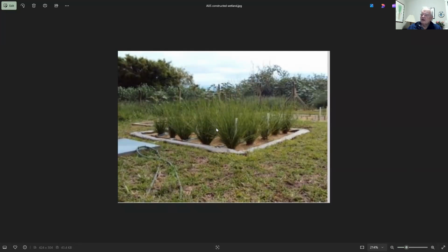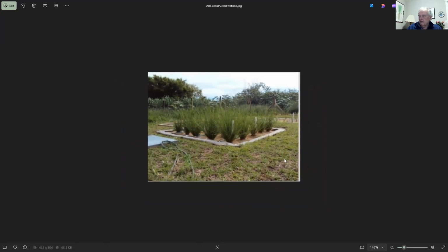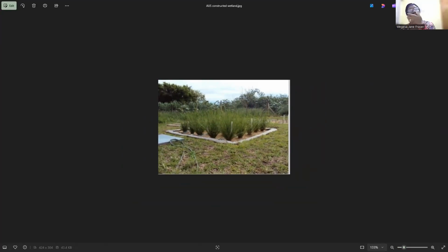Yeah. In this country where I live in the US, if you have a septic system in your garden, for your house, you have to put in what's called a drain field, where the water coming out of the septic tanks passes through into a drain field and is dispersed underground. Here, it's going into a drain field, which is actually a constructed wetland and is sealed. And the water which comes out of this is quite usable for irrigation purposes.